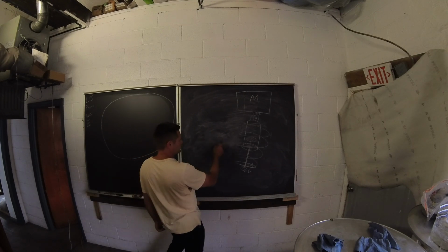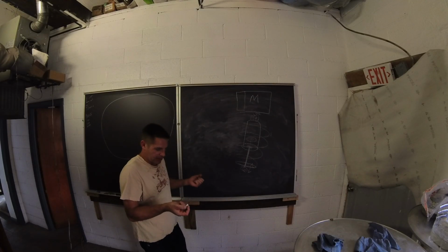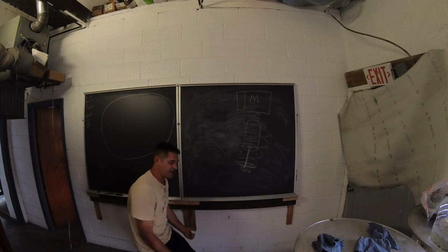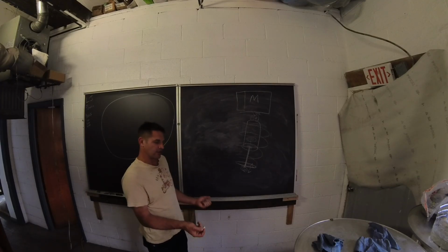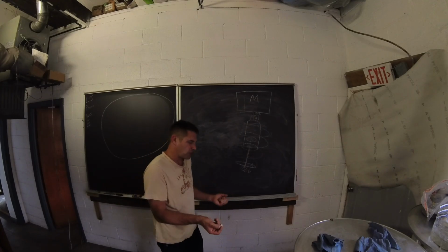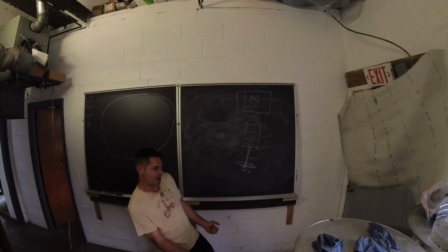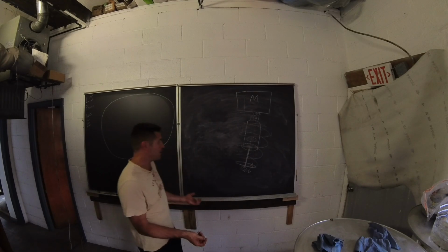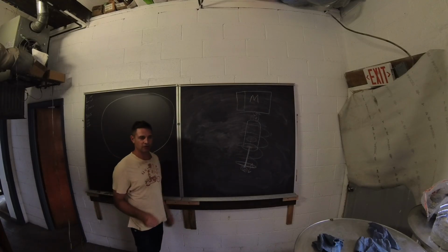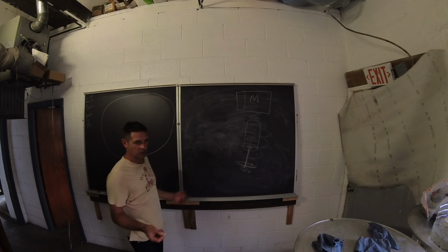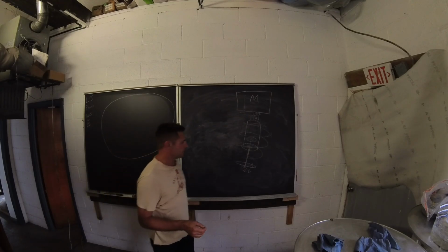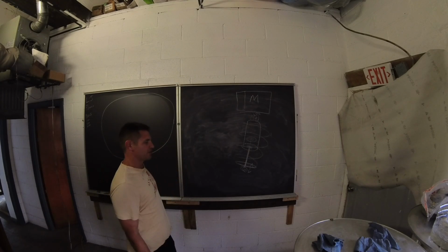It would go down to 4 inches, or might even go to 3 or 3.5 inches, and then it would come back, and instead of coming back to 6 inches, it would go up to 7 inches, and then it might drop down again to 4.5 inches, and eventually come back to that same rest point, because in a theoretical damper, a damper works in relation to velocity, not to position.